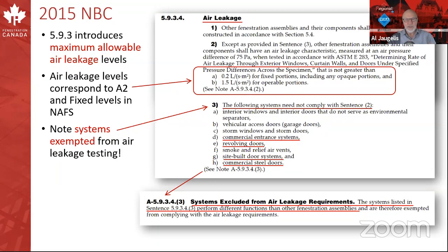Those low profile sills make it almost impossible. Essentially, we simply do not have products in North America that have low profile accessible sills that will have a water penetration resistance rating or an air leakage rating anywhere near as tight as what is required for a door that is acting as an environmental separator.